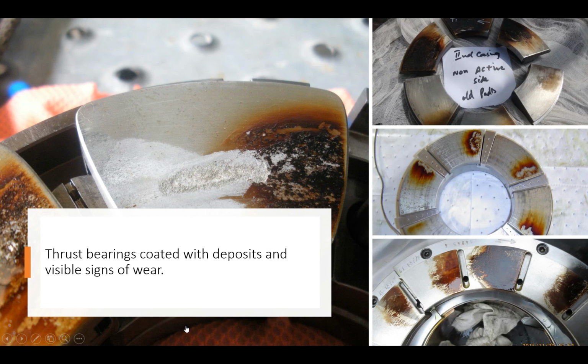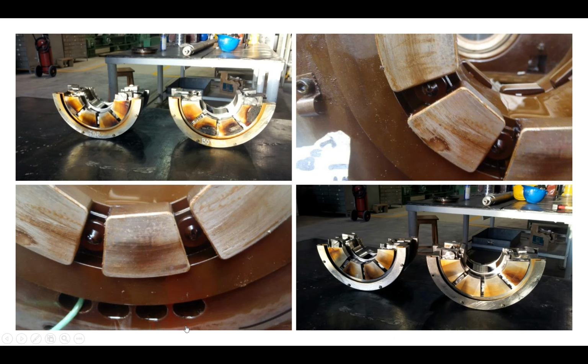Here also on these thrust bearings in the middle, you can see how we have a metallurgic effect taking place, or really damage. That's why often when the varnish is removed, you can see under the varnish already metallurgic damage occurring. Don't forget, what we will discuss later, is that when you don't have this hydrodynamic oil layer, you will absolutely have wear due to metal-to-metal contacts. Another few sets of thrust bearings are on the picture below on the right, left down picture. You see also these stripes typically happening.